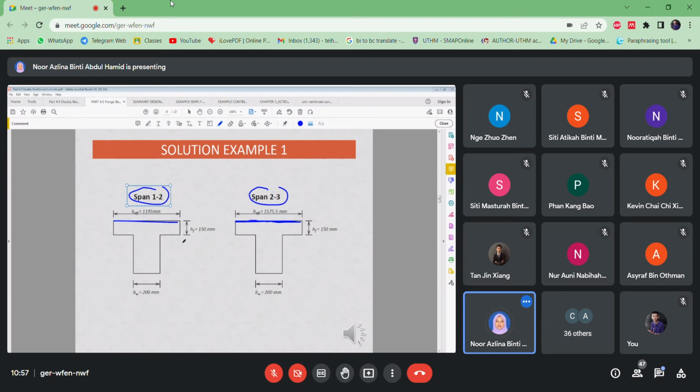So these both beams can be singular or can be doubles. Depends on the moment that applies on it. Is it these sections can resist or not for the beams, or might need another additional reinforcement for the compression reinforcement. So that means either design as a singular or design as a double reinforcement.